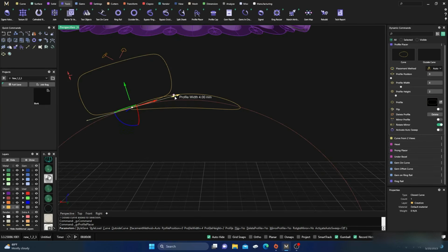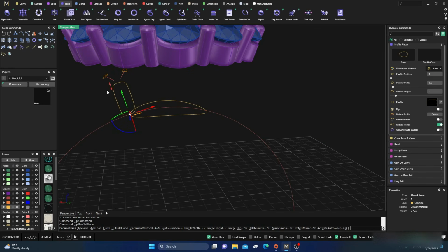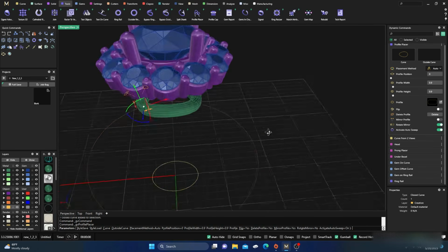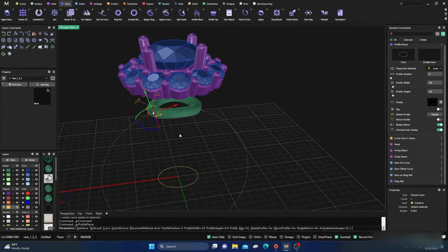And now I'm just going to do a little manipulation here. Again, if we do it right, we should be able to manipulate this all different kinds of ways. So I'm going to take that down to around a 0.9, and then take this down to around a 0.92. And instead of doing surface 2 or surface 1 and all that, I'm just going to select auto, which activates auto sweep, because it's going to be closed anyway. And then I'll take that.